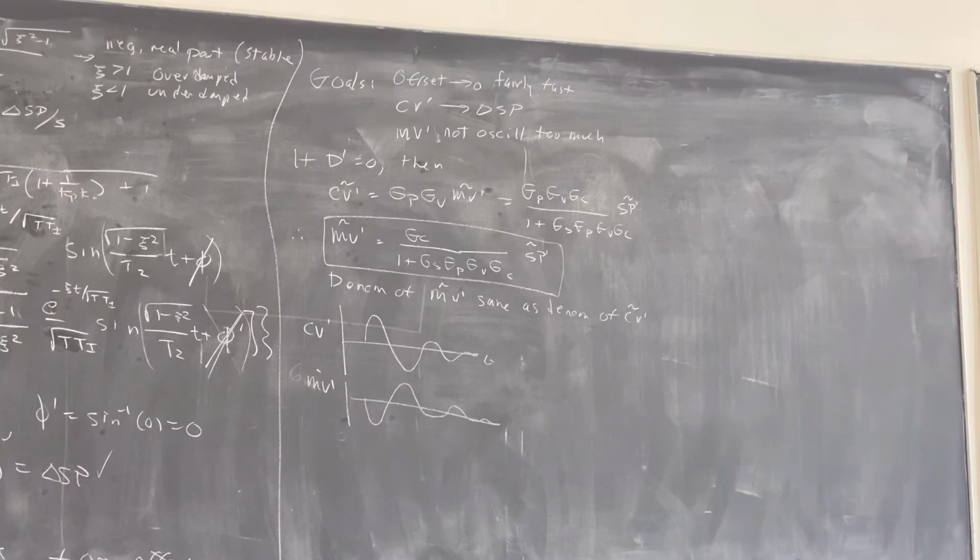In fact, you might try, if you have a good model that's analytic, taking the partial of the IAE, the integral absolute error, with respect to Kc set equal to 0, the partial of the integral absolute error with respect to Ti set to 0, and the partial of the integral absolute error with respect to Td set equal to 0.